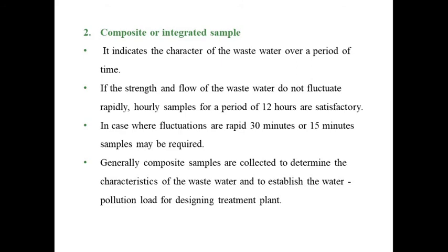Okay, so after the sampling of wastewater, what is the main objective of a wastewater treatment plant? To remove all the unwanted matter from the sewage, effluent or wastewater. That means to remove the organic matter, that is, to reduce BOD and COD, to remove suspended solids, to remove toxic matter, to remove nitrate and phosphate, to control the pH, and finally disinfection. These should all be done at the treatment plant, and these are the various objectives of wastewater treatment.